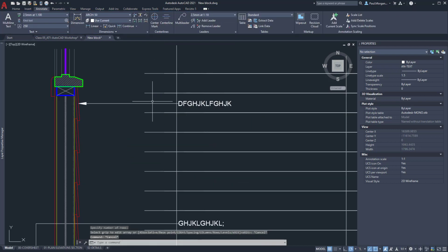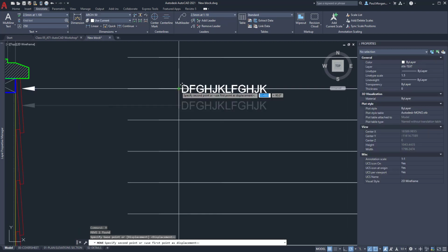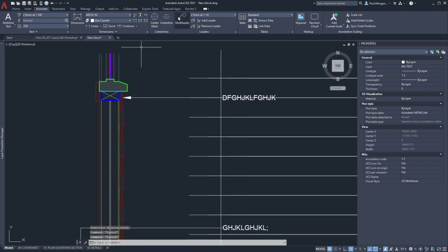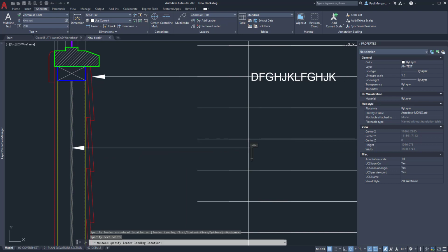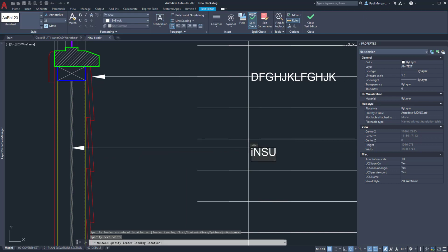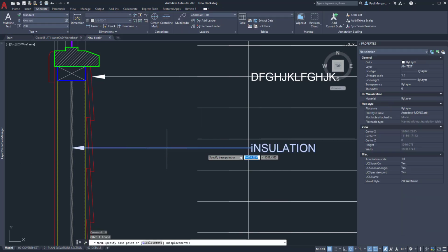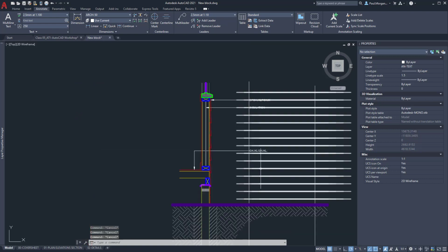Now, why have I done this? It's so I can then line these up as best I can. So I'll go, okay, I'll put this on that line there. Then I know the next multi-leader can go on the next one. So it doesn't even have to be there to begin with. I can say, oh, all right, I'll do the one for installation. So I come down here so it doesn't snap to the top. Click once to start once again. And this will be installation as an example. And then I'll click on this and I'll move this up to the next line like so.